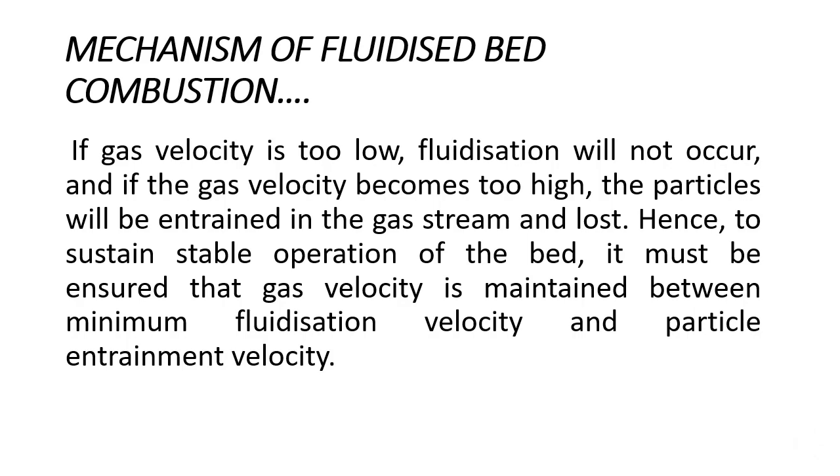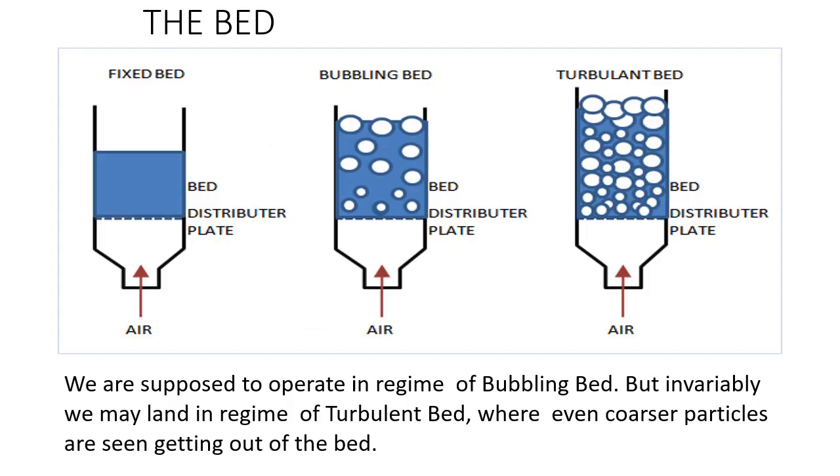Here you see the bed. You see the fixed bed with the sand, then you see the bubbling bed where the fuel and air are supplied, and then the turbulent bed. Generally, we are supposed to operate in the regime of the bubbling bed, but invariably we may land in the region of the turbulent bed, where even the coarser particles are seen getting out of the bed.